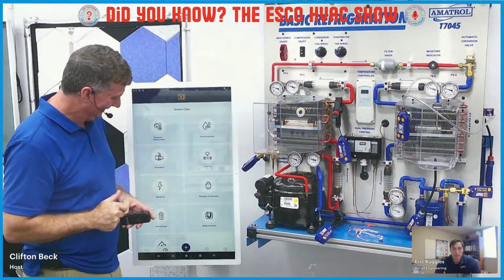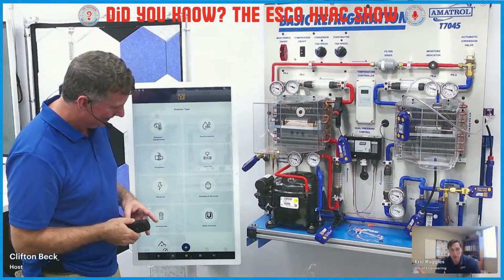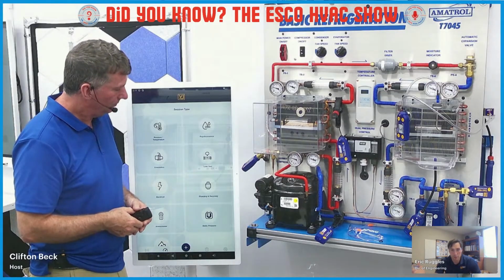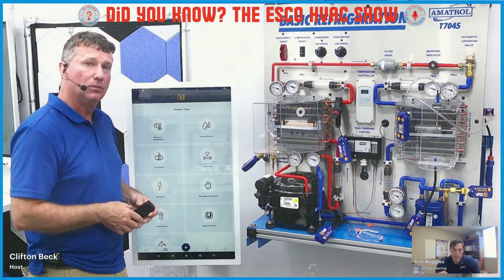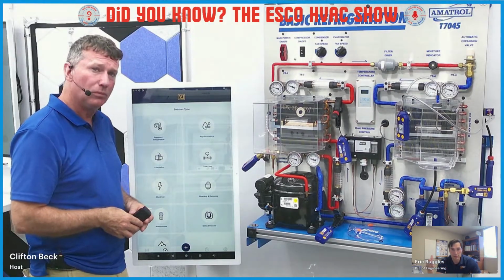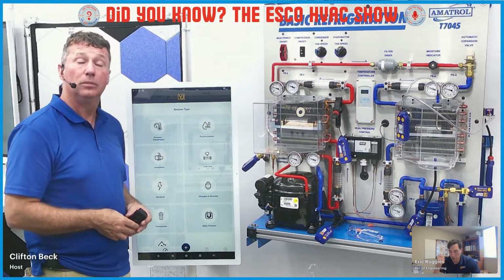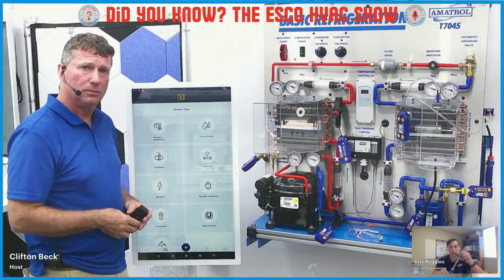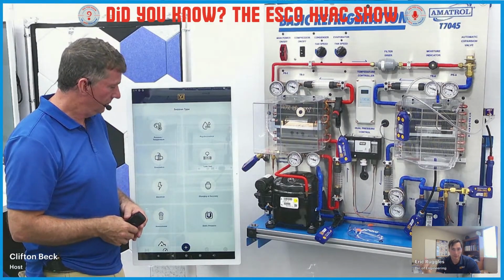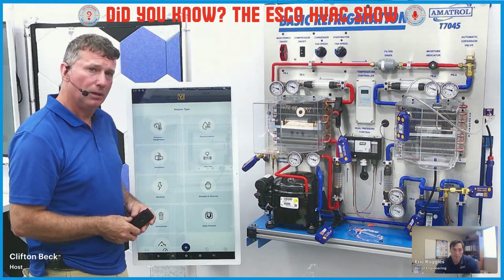Are we ready? Yeah, go ahead. The last few in there are your charging and recovery. That would be a connected wireless scale. You can track your charging or your recovery of quantity of refrigerant and save that. The anemometer session, again, is with a hot wire anemometer. It literally asks you what size the ductwork is. It'll tell you how many traverses it has to do, how far apart they are. And then all you have to do is click the button on the sensor itself. It'll walk you through each time, and then it'll spit out the volume of air as well as the feet per second of the actual airflow.